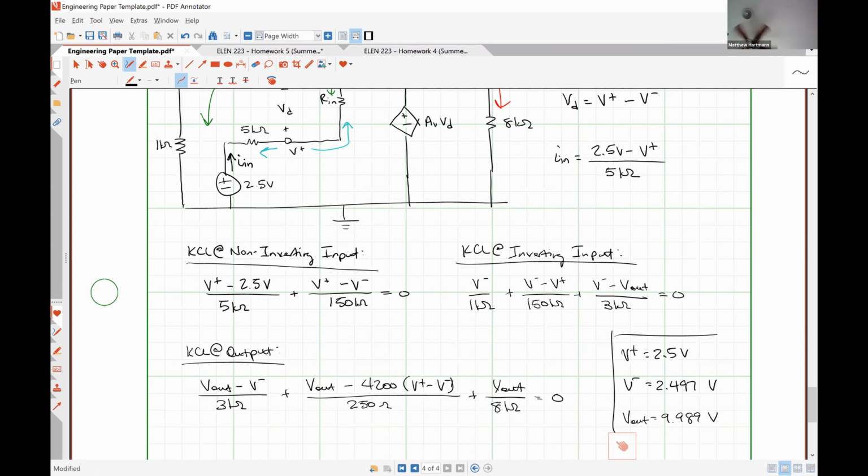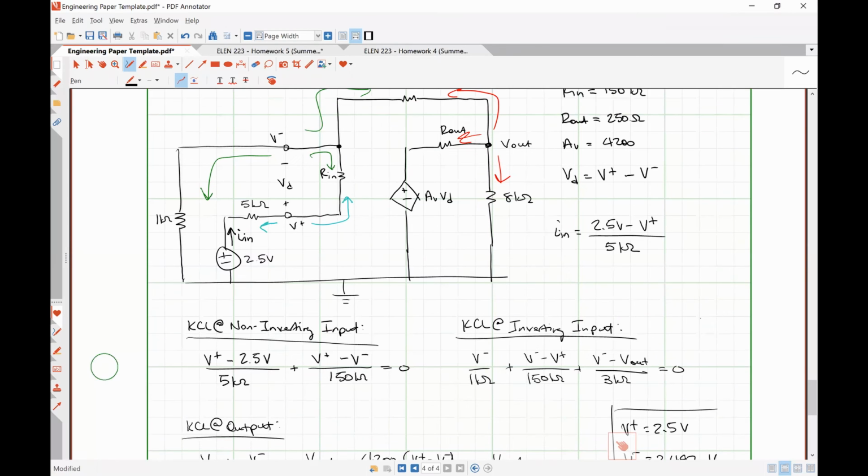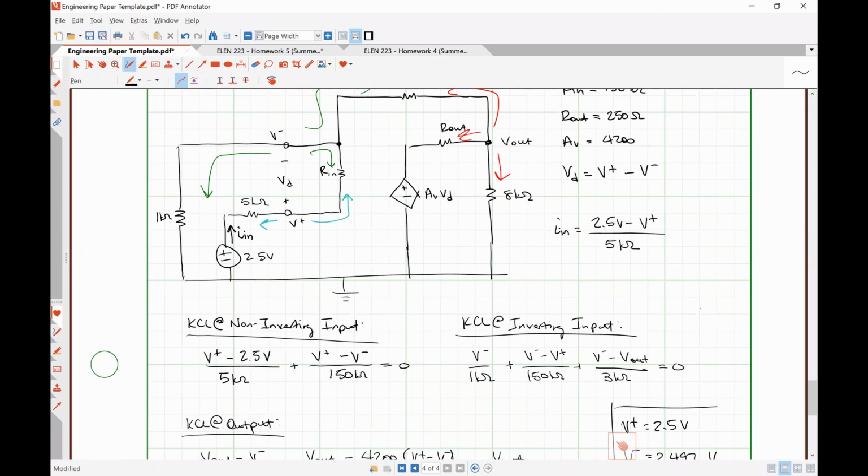And it's vastly different because it's a non-inverting amplifier versus an inverting amplifier. So the reason it was 5K in the example you did was because the current could flow around the op amp. Effectively, yes. And here we're forcing it to all flow into the input terminal. All right. I was just a bit confused. Thank you. Nope, no problem.